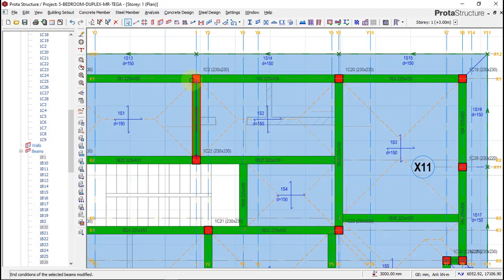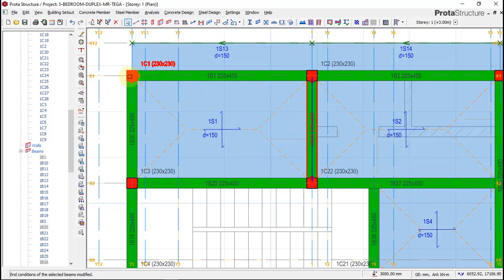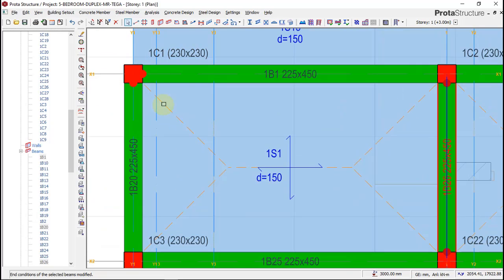Now the reason why I do this is because most people don't do it. Most people just say, okay, I want to leave it that way and go ahead. The reason I do this is that when we perform our structural design, we look at stability and also cost. When you do this, you're invariably reducing the quantity of reinforcement that this beam would have taken on this end.